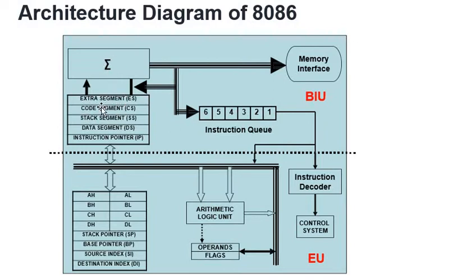So the segment register content will have 16 bits of data. The instruction pointer register will be holding the value of the offset address. The decimal digit 0 added along with the least significant byte of the segment register content will convert the 16 bits in terms of 20 bits, as the 0 includes 4 zeros, which will add 4 zeros to the lower byte. So the 20-bit converted value will be added with the instruction pointer to access a particular memory location of the memory block.